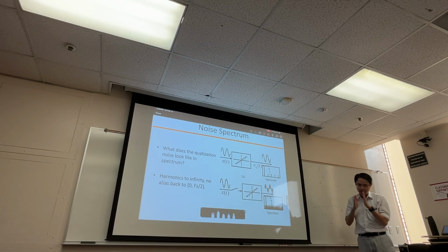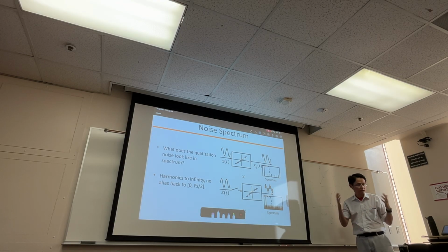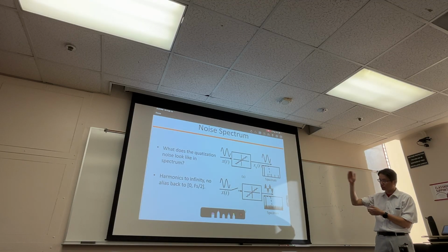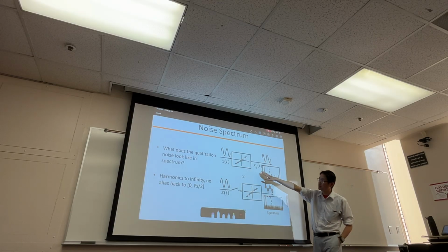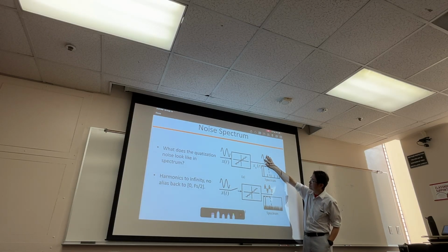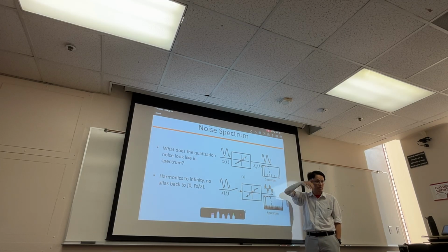By the way, this is just one type of non-uniform sampling ADC. Like I said, there are many other types of non-uniform sampling ADC. This is called level crossing, where you really just do amplitude quantization. This is the output waveform, so the samples are generated depending on when your input signal crosses a certain level.